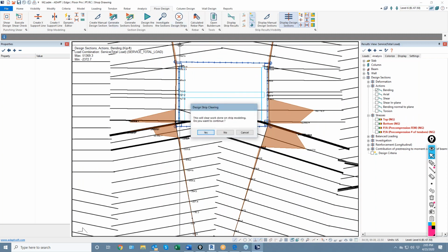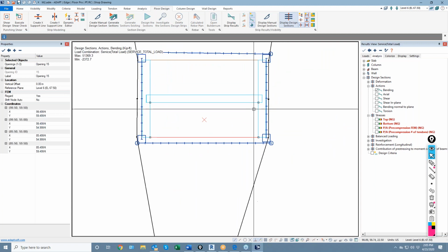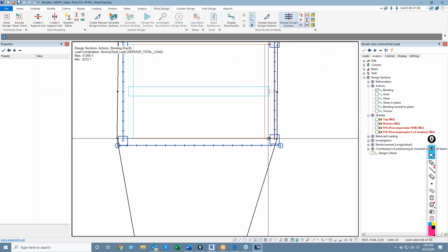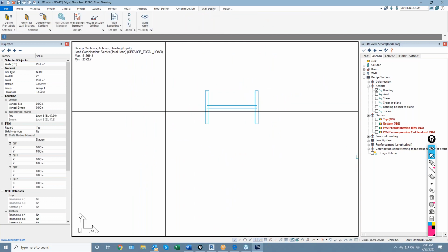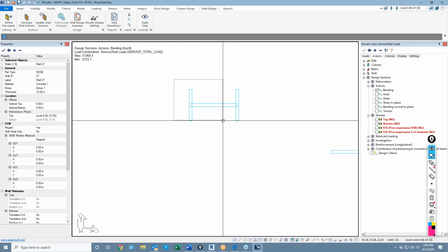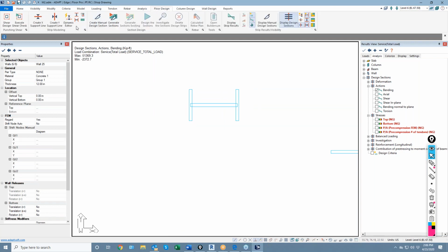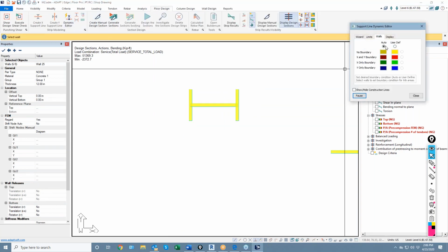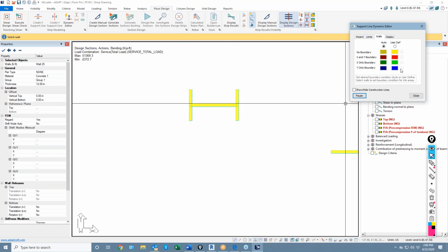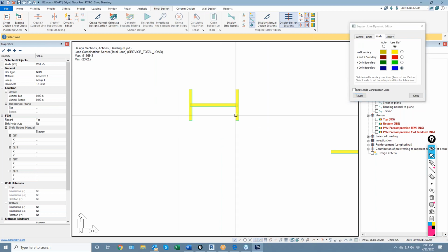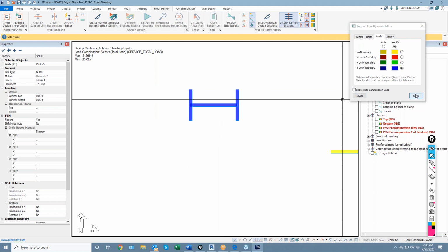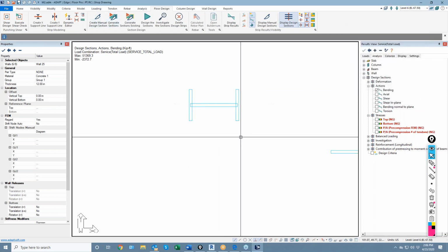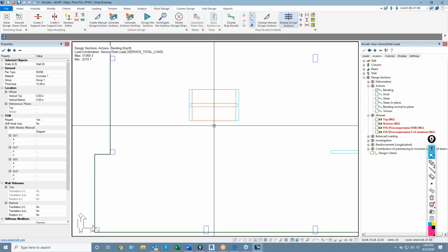Let me try one more thing before we give up here for today. I'm going to select this wall. Actually, let me go to my wall design just to isolate the walls. And what I'll do is create a boundary. So I'm going to say these walls, if we go to floor design, dynamic editor, walls, we can say these walls here, I want those to be a boundary for Y direction support lines. So we're going to change these. That means the program will not cut, should not cut the sections into those walls. Once I've done that, we'll generate the cuts again.